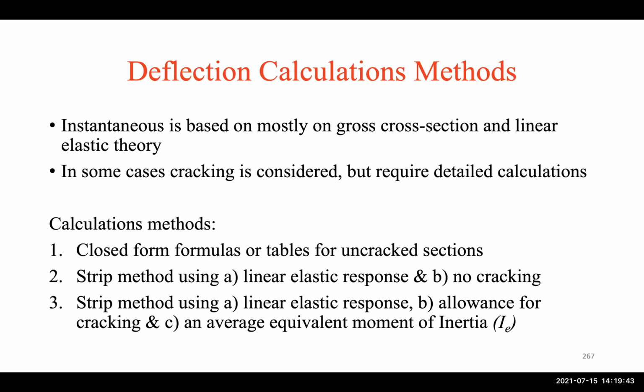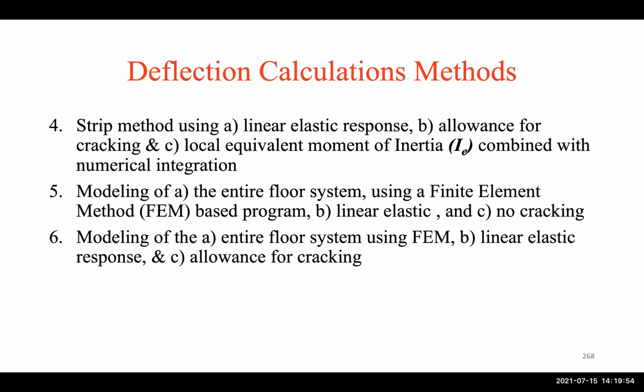So we did the equivalent moment of inertia. We did that in reinforced concrete design for beams. But again, here, since we're talking about plates, plate theory has to be used. Then there's the strip method using linear elastic response, with allowance for cracking and local equivalent moment of inertia combined with numerical integration. That's a little bit more complicated than the previous one.